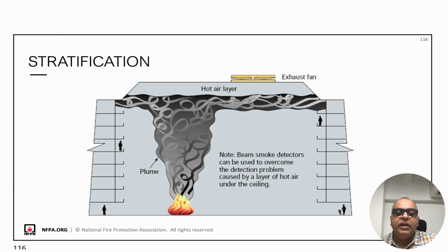This picture shows a fire generated at the base of the atrium of a hotel. The heat from the fire rises, carrying the smoke and hot gases upward. The rising column is called the plume. A hot air layer forms below the ceiling. As hot gases collect, they spread out along the ceiling. Over time, a thermal layer forms, shown as the dark swirling smoke layer at the top.